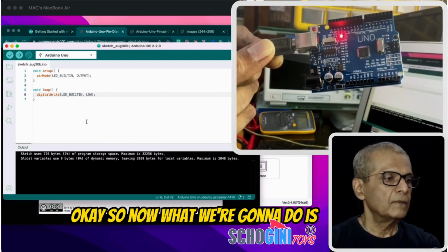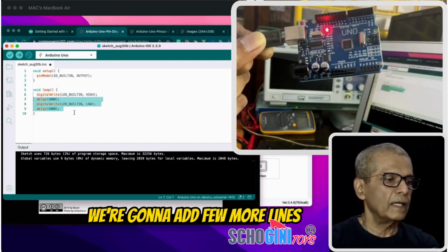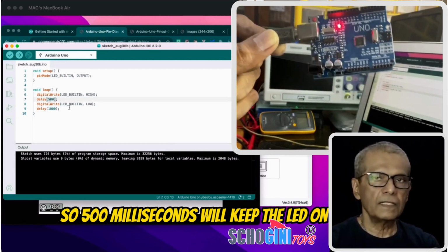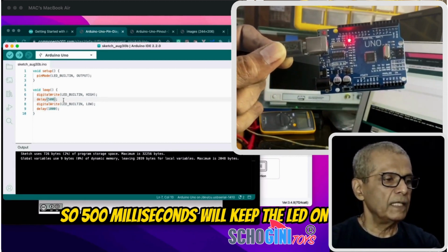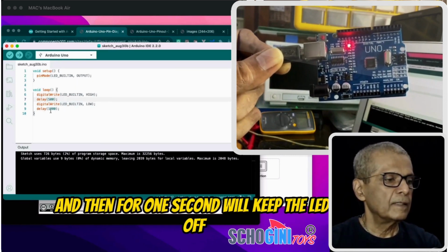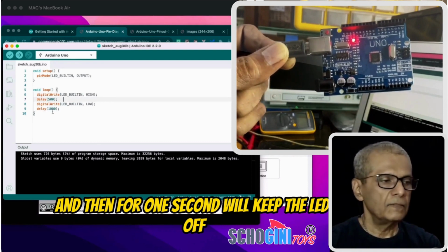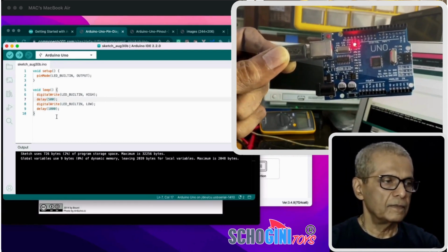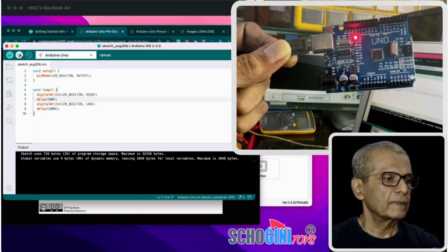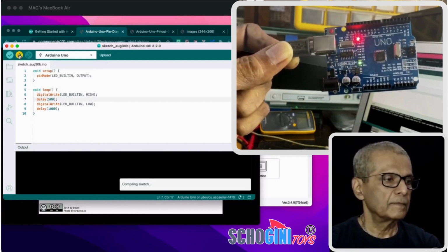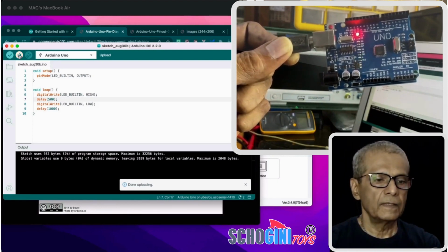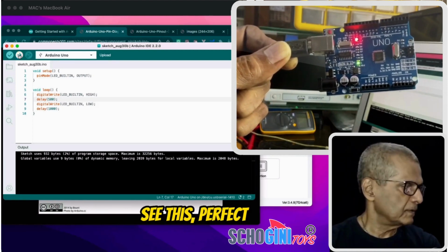Okay, so now what we are going to do is we are going to add a few more lines. So 500 milliseconds we will keep the LED on, and then for 1 second we will keep the LED off, and this will loop. Shall we upload this? Done uploading. See this?